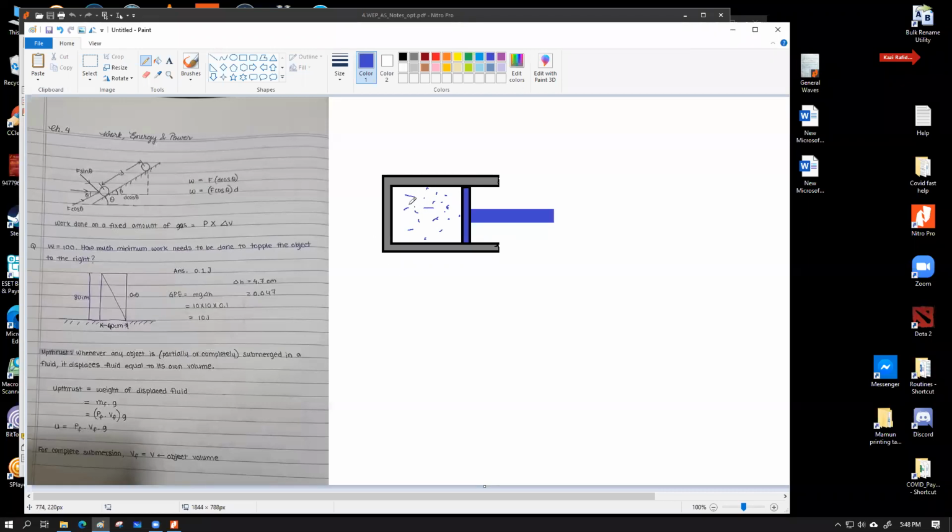So let's say currently the pressure that is working on this side of the piston is atmospheric pressure, and if the piston is maintained at a fixed position, then you also have to understand that the pressure from inside the gas is also exactly that much. So these two are equal. That's why the piston is held up in a fixed position. There is no gap between the cylinder and the piston at this border, but there is a gap inside the cylinder. So it's a frictionless yet movable scenario, but the gas cannot leak out. That's the generalized situation that we're assuming.